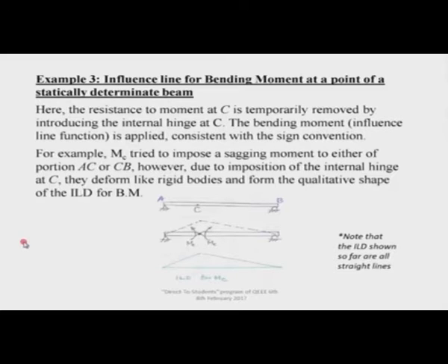Internal hinges, you might have seen them when you are traveling by ship and you get down at the jetty. One platform is projected from the ship, and from there something is hinged and that is touching the ground or the jetty. So, even if the ship rolls and has a pitching motion, going up and down, due to the internal hinge the system does not develop any stresses. So, it is a very nice way to release one of the stress resultants.